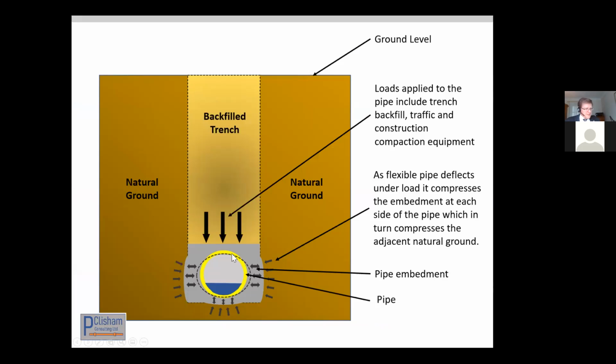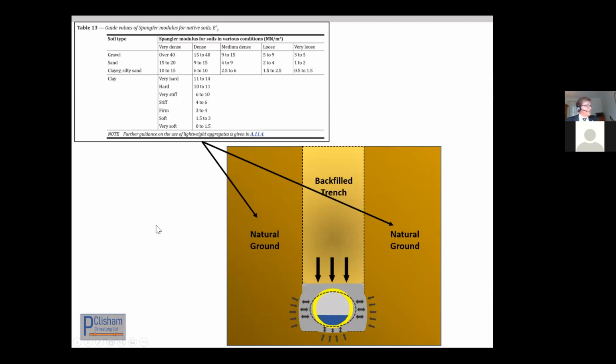So what's happening is these loads are carried by a combination of the pipe itself, the embedment around the pipe, and the natural ground conditions. And it's the combination of the 3 that carry the load. And no matter where you go in the world, whether you use the German standard, the French standard, the American standard, they're all based on these same principles. They might use different factors, different equations, but the principles are the same.